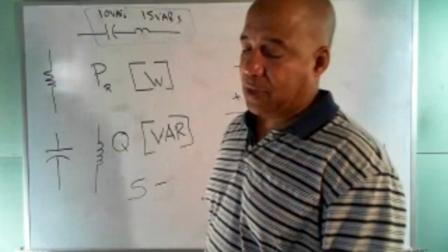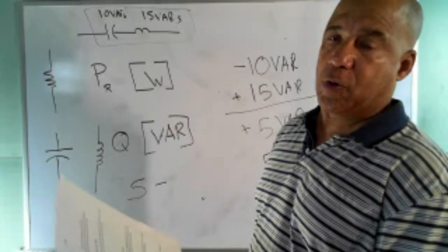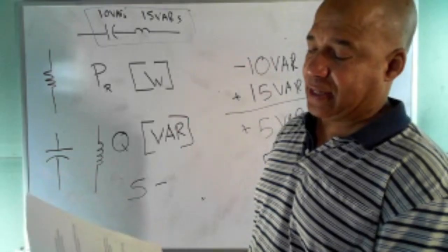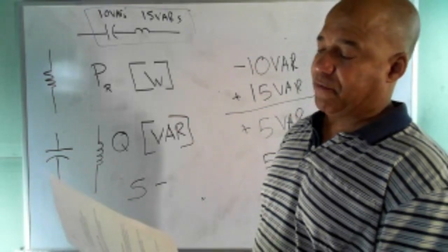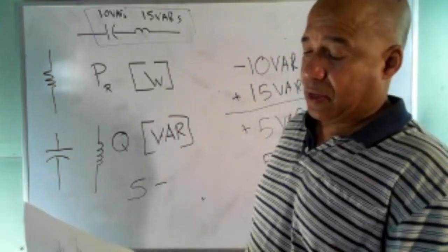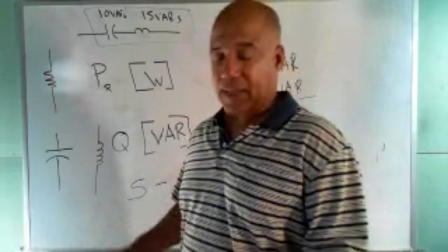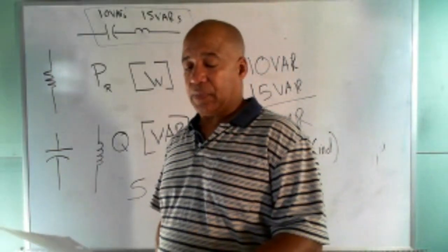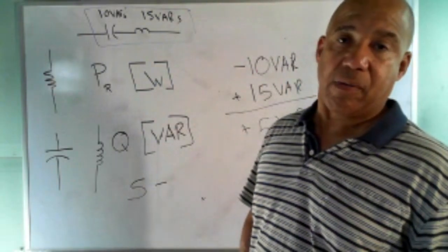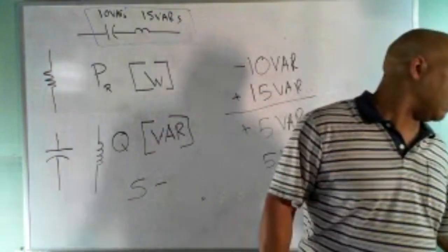And then the last one is apparent power. They use a symbol S. The unit is a VA, volt amp. And it says there the power value obtained in an AC circuit by multiplying together effective voltage and current, which reach their peaks at different times, because there's a phase difference now. Because resistance is being mixed with the reactance, that causes them to peak at different times and gives you the phase difference. And then at the very bottom it says S is determined by the power triangle. So let me relate it to DC.